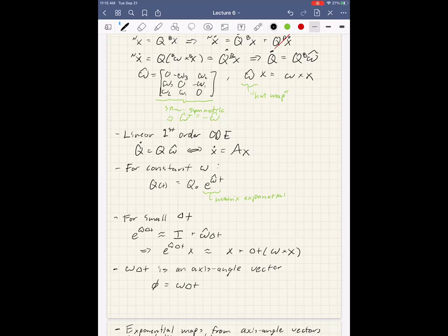Yeah, so practically speaking, where it gets bad mathematically is really related to Nyquist sampling. You think about this as sine, cosine, oscillating rotation stuff. You need to sample densely compared to the period of oscillation. So if this thing's wrapping around, it depends on the rotation rate, basically. But from Nyquist, you need to sample at least a couple times per rotation period, right? So that's really what it comes down to. Practically, you want to go a lot faster than that, right?